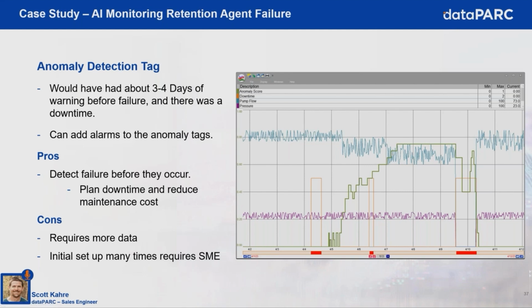So as the anomaly score is rising, you would also have a set of probabilities that individual input variables are contributing to this anomaly. And we don't have a trend of that here, but that information could then drive your investigation into what's causing this anomaly, and perhaps you would see some high scores on the pump coming out of the tank, or maybe the agitator amps on that tank, and you'd go and find that agitator broken, and the fact that retention aid chemical was not being mixed properly.